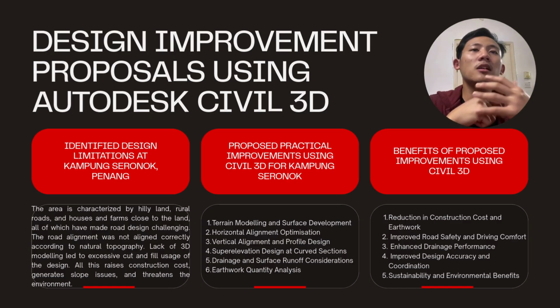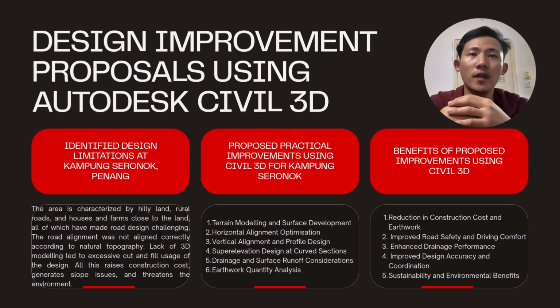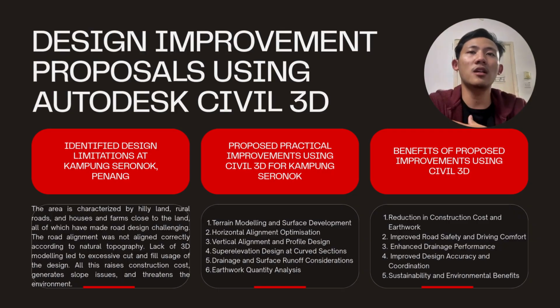The vertical alignment was also improved by smoothing the steep gradients, making the road safer and more comfortable, especially for heavy vehicles. In curved sections, superelevation was applied to enhance vehicle stability, particularly during wet weather conditions.